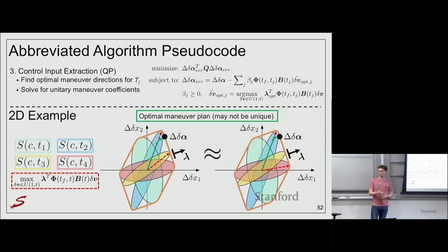Can it not be modeled with the optimal times as an optimization variable as well in the SOCP? So it's not without iteration, or well, the times are solved here as part of the problem. That's the difference with the standard CVX. It's the key advantage of this method. We are solving for the maneuver times.